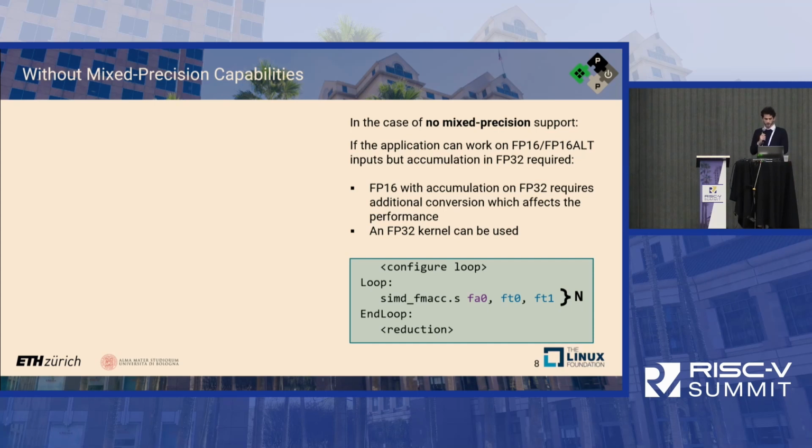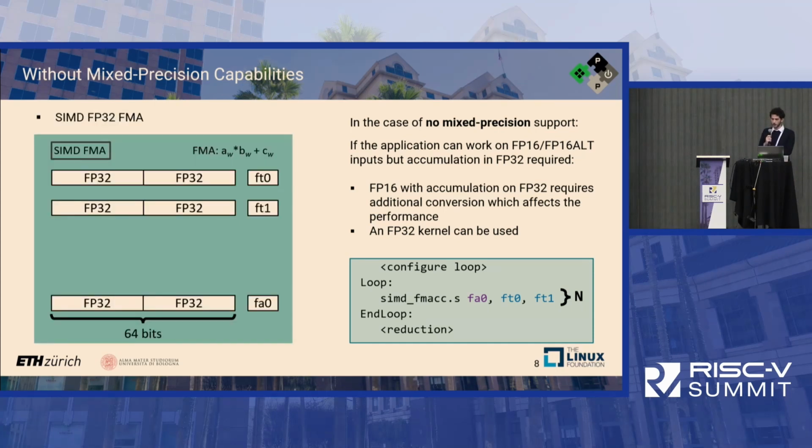If we proceed this way, we consider a kernel that has FP16 or bfloat16 input and accumulates in FP32. Same for kernels that start from 8-bit inputs and accumulate in FP16. In this case, if we consider FP32 accumulation, we would be able to map 2 of them in a SIMD way.